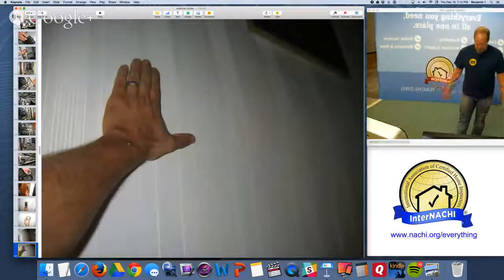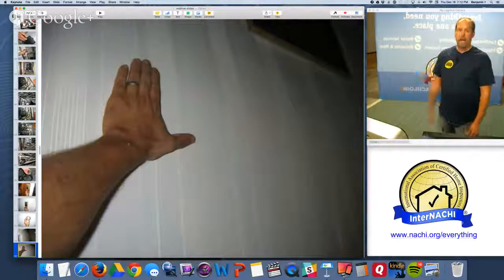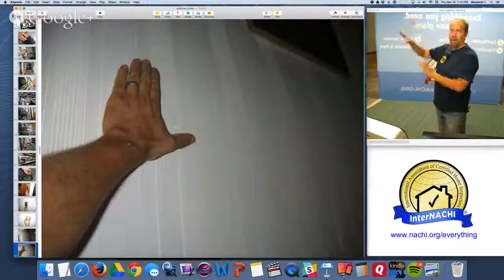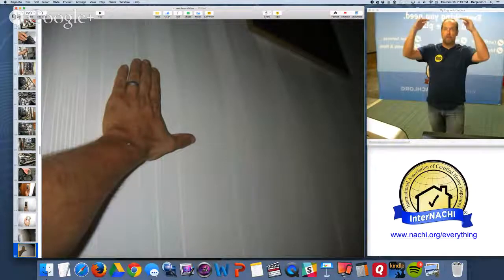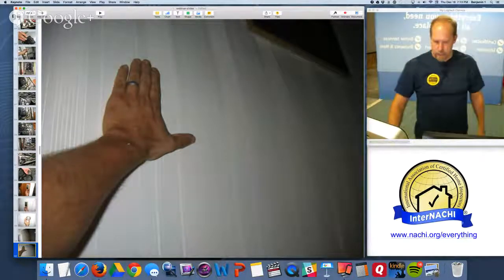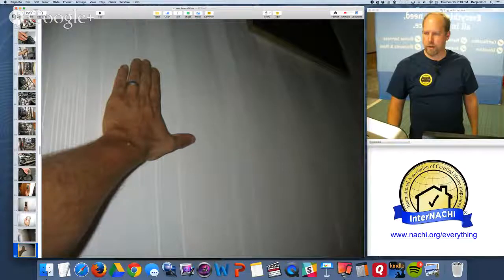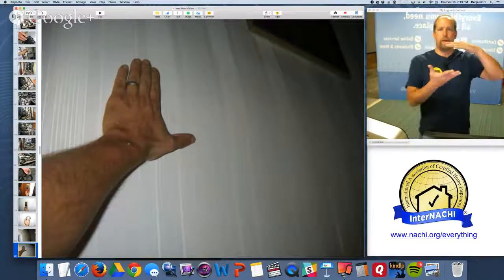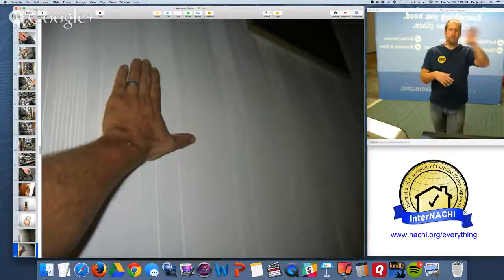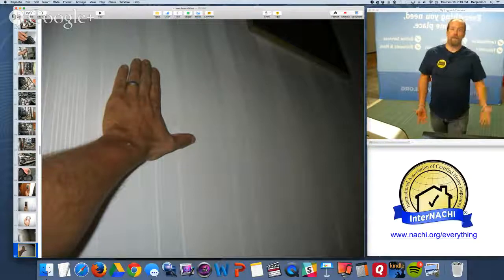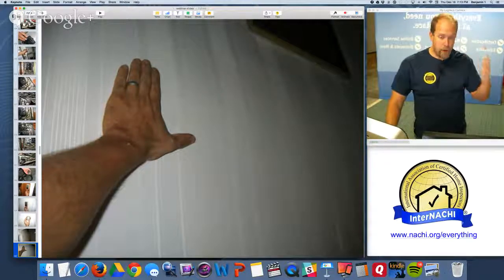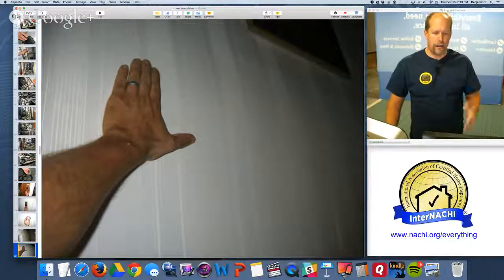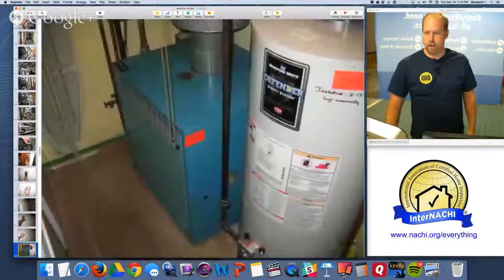Trip hazards at the stairs, railings. We have surfaces all over. Look at the floor surfaces, the wall surfaces, ceiling surfaces, looking for watermarks, and this huge bulge in the structural part of the house, probably settled at the band rim joist area, and they never fixed it. Or maybe there's something continually going on. I don't know. I'm going to call it out and ask for further investigation.